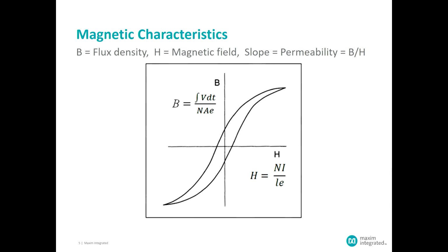That curve has a thickness to it because it takes energy to be able to move up the curve, and as you increase the current, the flux density moves up on the right-hand edge of that curve, and as you terminate the current and the magnetic flux returns back to its low position, it comes back down the left-hand side of that curve.